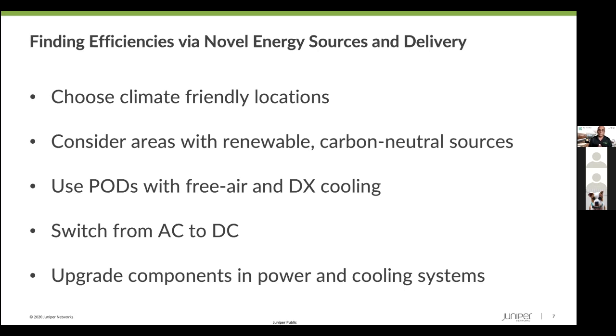In terms of all the systems that are used in power and cooling systems, you don't have to change the components, but you can upgrade them. For example, one simple idea is to use variable speed drives in motors and fans. So you can run the speed of the motor or the fan based on actual energy usage rather than running at a fixed speed, and that leads to lots of energy efficiency. And by the way, those sorts of technologies are not yet widely deployed because every hyperscaler or public cloud provider thinks that's their intellectual property, so they tend to invest in it, right?